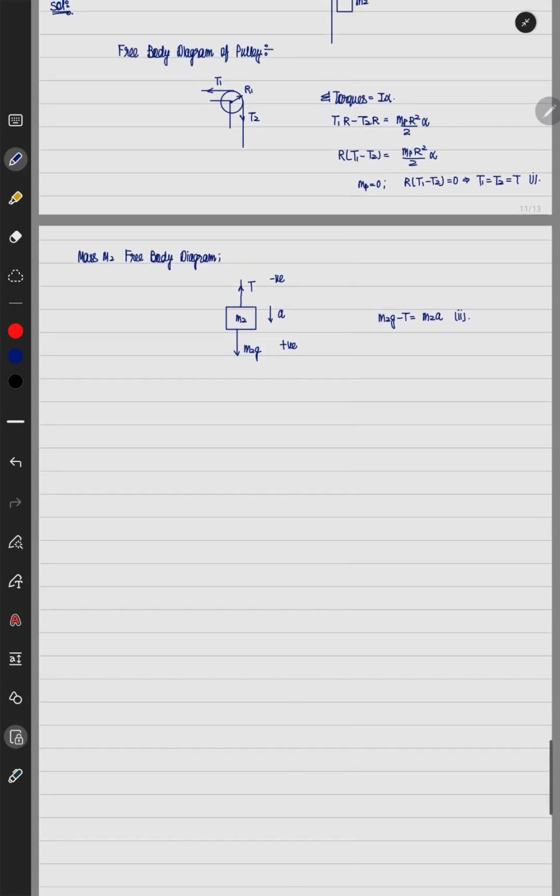The third thing that I can do is apply the mass balance on mass m1. So, free body diagram of mass m1. m1 is the mass. The string is pulling this mass in this direction, so this is tension, and there is one force which will be acting due to the fluid which is kept in between the surface of the block and the table surface.